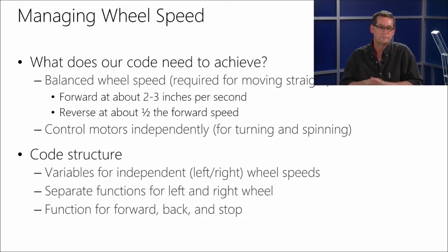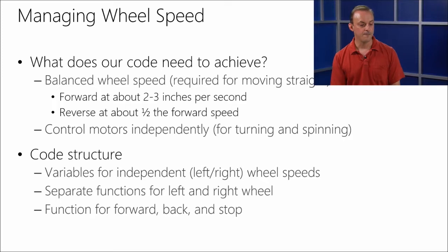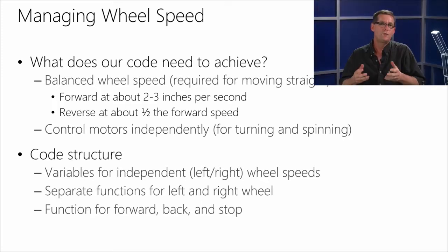Short and sweet. All right, let's talk about some of the specifics in actually putting this thing together. Okay. So now we've seen how we have one wheel and we can turn it forward and backwards. I can't remember, Paul. Did we see that servo turn a little bit? We talked about the center speed. Now that we have 2 wheels, we want them balanced in their speed, right? Because if it's not balanced, it's going to go in an arc instead of straight. We did. We saw that was not calibrated correctly.